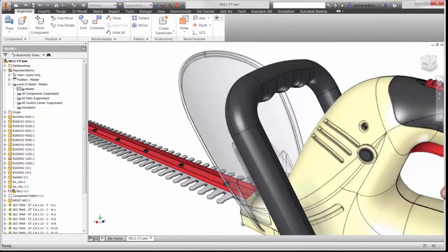Typical load conditions on the part cause a large amount of displacement. Linear static studies may provide designers with the highest stress location or displacement in the design. However, in order to gain high-fidelity results, the nonlinear static study is required in cases such as this.